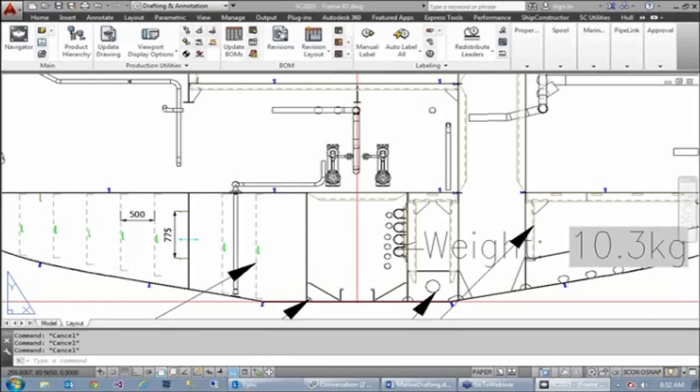How to generate an arbitrary view. In this case, of course, the main views are the primary views. But if my plate part was skewed in any way, I can generate a view from that as well. It's quite easy to generate one for any of the skewed directions, and it automatically handles it based off of the orientation of the plate part. I can also theoretically rotate my view as well, but you don't really want to get into actually rotating the bounding box in the section, though it is possible.